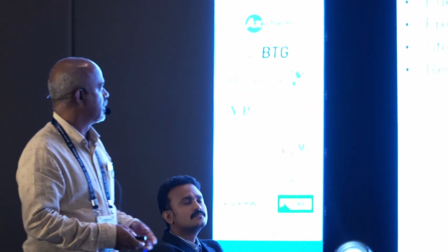So the transition, yes. When we do this, there are two areas. One is stability, second is agility. For stability, the two sigmas are low for all your process. Agility means when you make a step change, change the grade, or have any upset, how long it takes to bring it back to the original state.